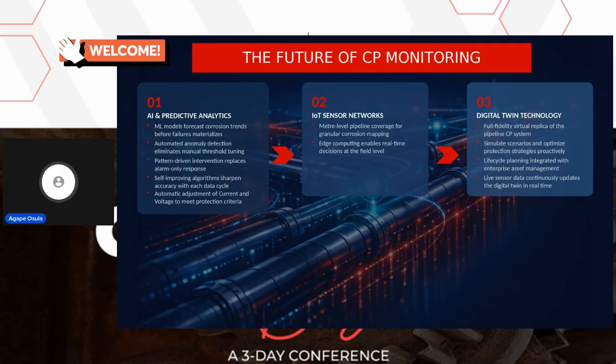However, for those systems currently, the reference electrode for the TRU is the one close to the TRU system. It's not the ones along the pipeline. So if it detects a potential which is beyond a particular level at that one location, it can make deductive changes. But where we are going is that across the entire network, it takes potentials, and based on all those potentials, it makes deductive changes.